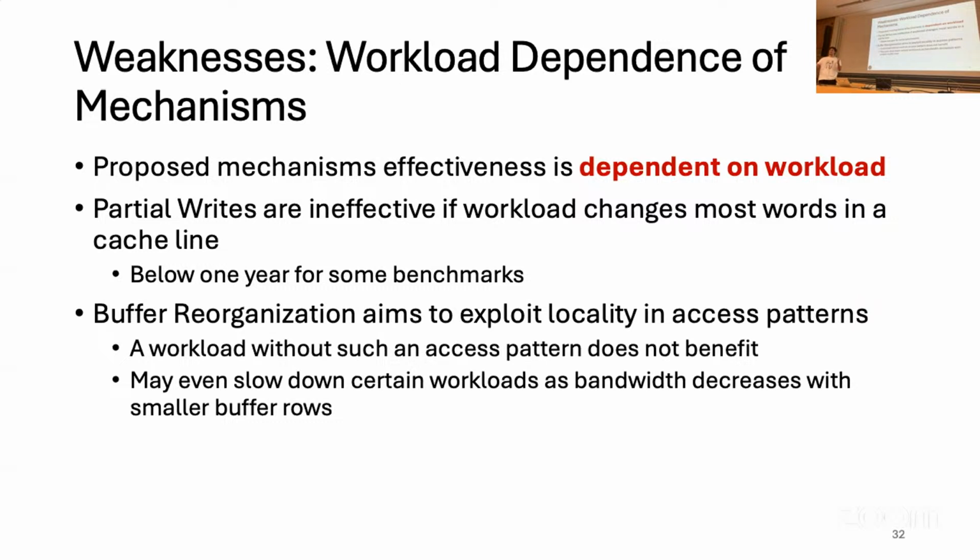You remember we reduced the number of sense amplifiers, so we can sense less data with one read operation. If we want to get the same data that we got with one read before, we may now have to do more than one read. That's why the bandwidth might decrease.